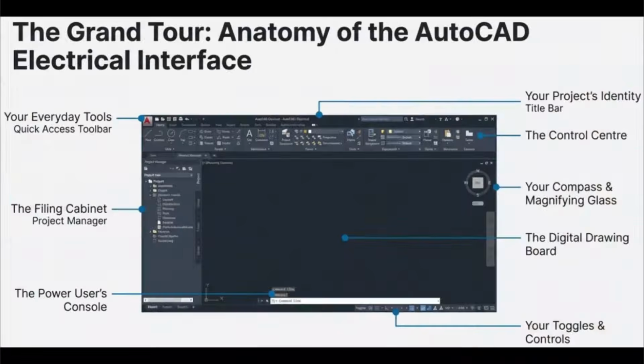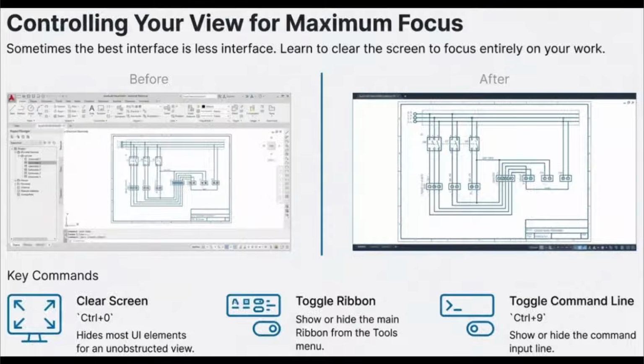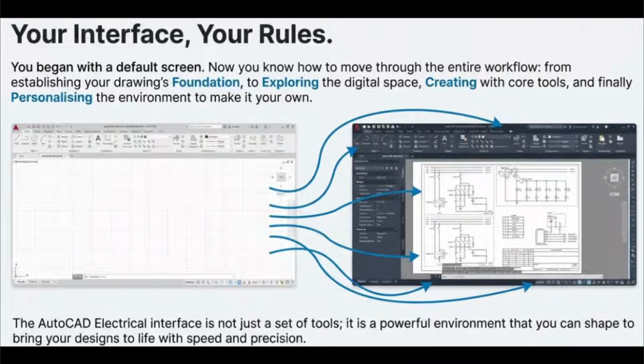And when we're in that utility mindset, let's talk about data integrity. We often overlook purge and recover drawing. Okay, so why should a user be using purge all the time? I mean, if you think your file is clean, why bother? That's a great question. Because purge removes unused or residual items, things like old block definitions, layer filters, line types you're not using anymore. So it's just digital clutter.